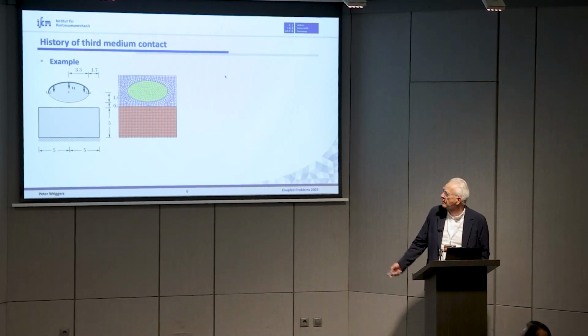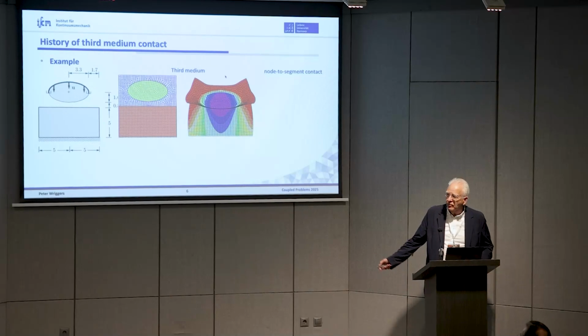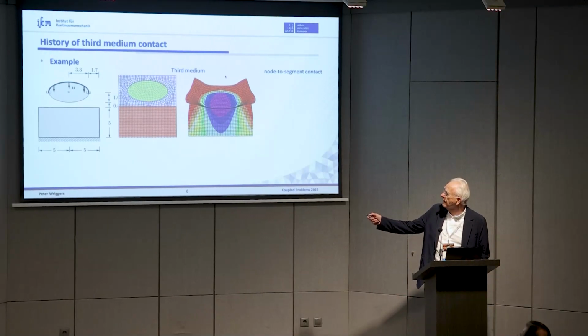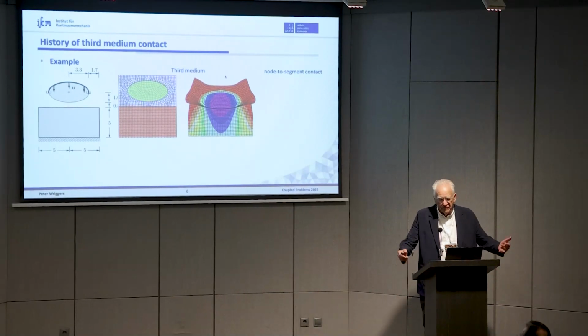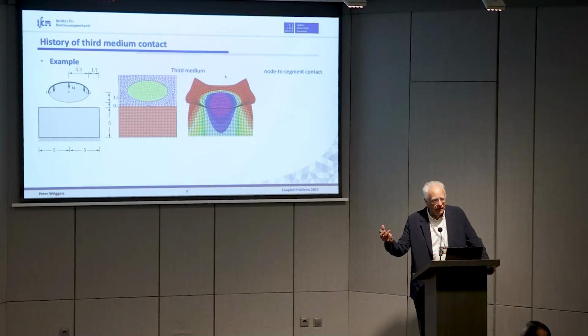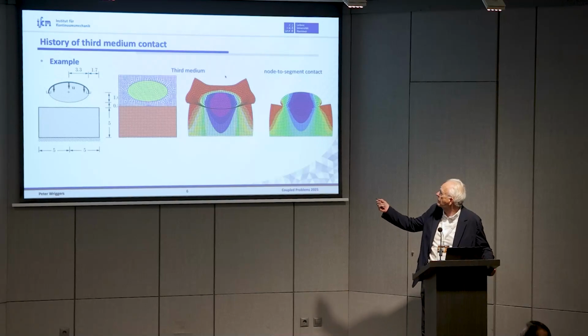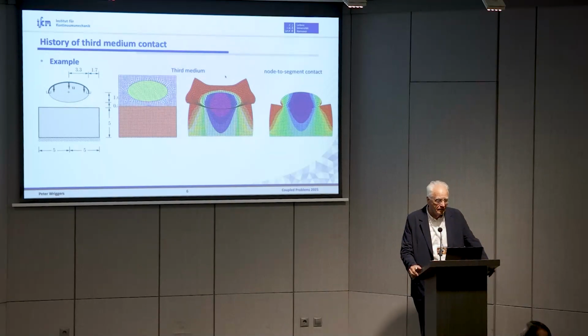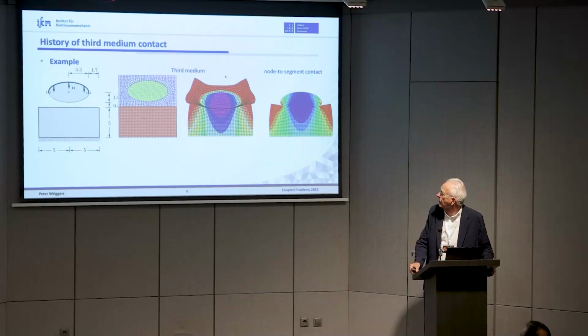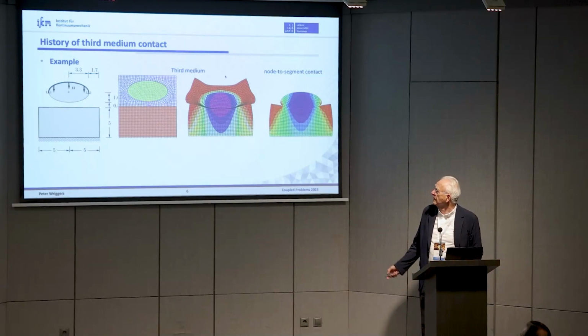This is the mesh, and this is the result. And you can already see that there's some bulging here, which, okay, is because it's a large strain, but the result is not bad. This is sort of a solution. It's a standard contact problem, node-to-segment approach, and you see the stress field is quite okay. What you also see is that we could not fulfill the gap at that time very well. So we had to do something in this direction.